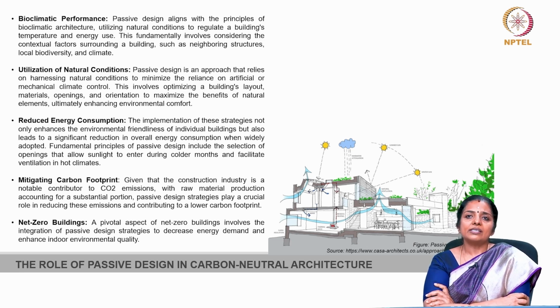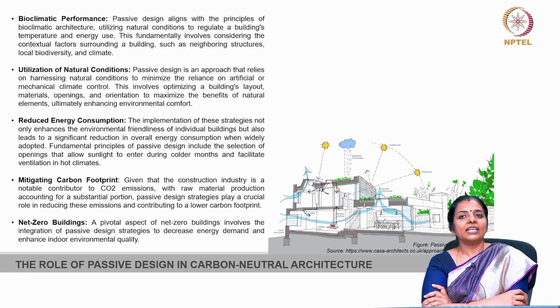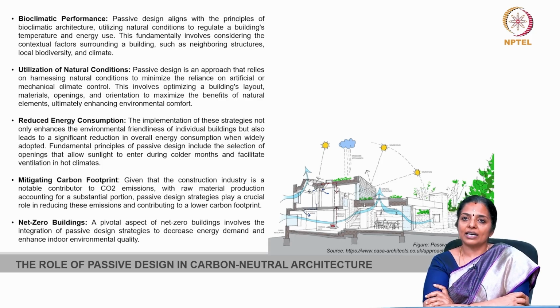The key principles include selecting openings for sunlight in colder months and facilitating ventilation in hot climate, but at the same time optimizing the openings to ensure less solar gain. Passive design plays a crucial role in mitigating the carbon footprint of the construction industry, a significant contributor to carbon dioxide emissions.